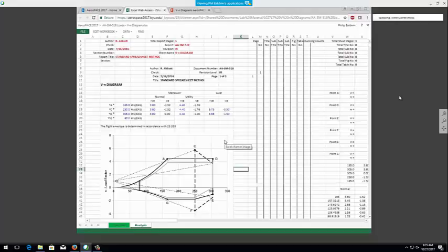So now we have just CL max and basically your launch velocity. And we get a relationship here, which you can see at 6 meters per second takes a lot more power. It seems to dominate relative to other things. If I increase this from 20 feet per second to 30 feet per second, it drops, and now it's very low. So if you get a good launch, if you get a very strong throw, or you have some free velocity in the form of wind, it's very easy to launch the aircraft. If you throw very weakly, it's extremely difficult. All right, so 30 feet per second is really difficult to actually launch the plane that fast.